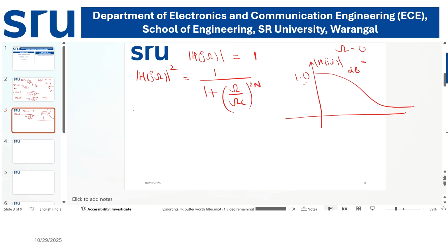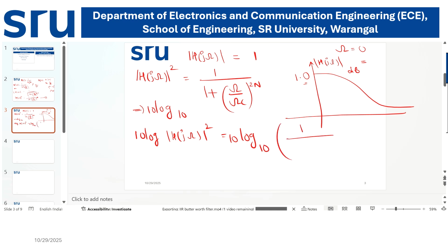Now if I apply 10 log on both sides, in terms of dBs, then I have 10 log base 10 of the magnitude of H(j omega) whole square equal to 10 log base 10 of 1 by 1 plus (omega by omega c) whole power 2n.